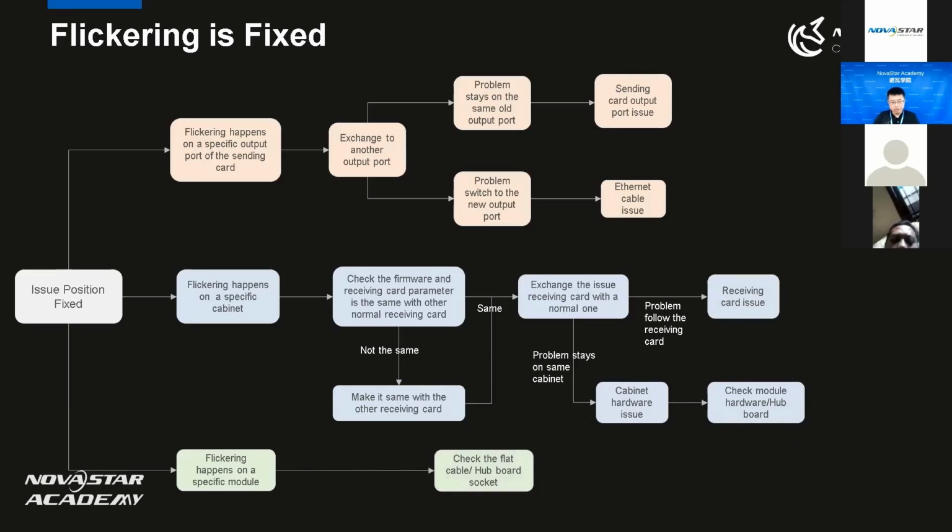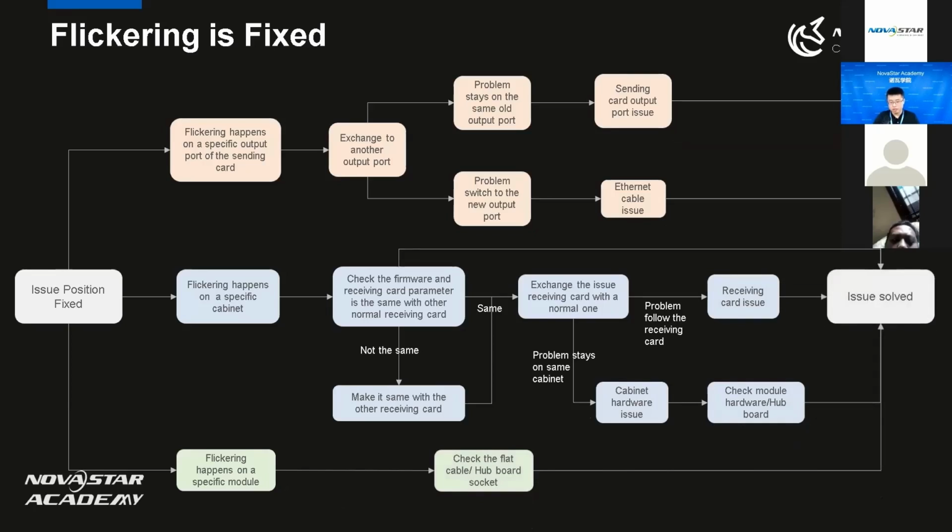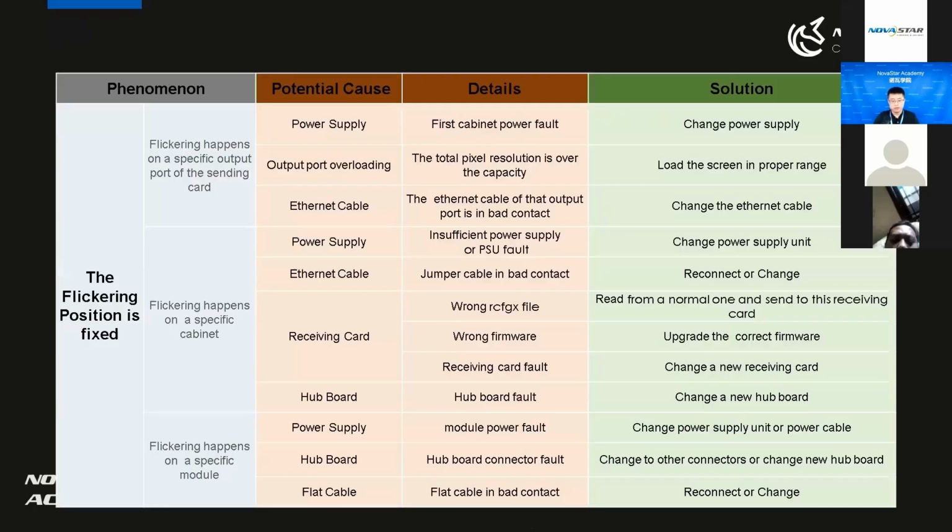And if the flickering happens on a specific module, you can try to check the flat cable and hardware socket. So finally, we will get the issue solved. And here is a picture that lists all the potential causes, and we have solutions for that. So maybe you can take a picture to keep this as a record.